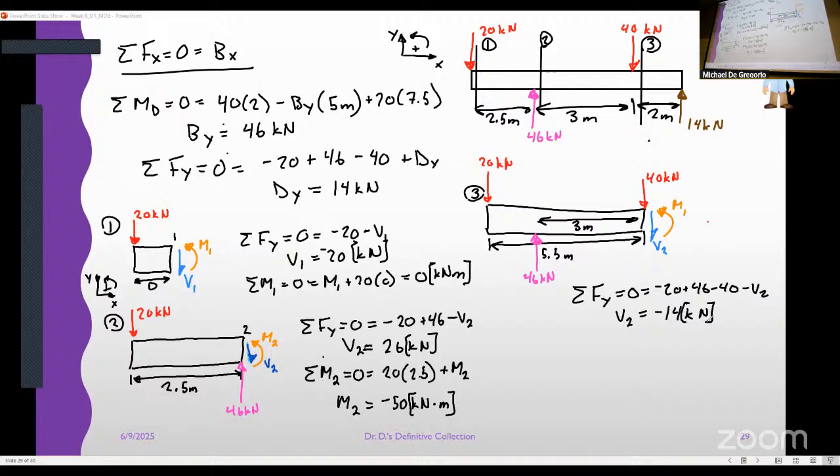And these are point loadings, and if you were to cut this someplace before 3, let's say I cut this here, let's call it 2.5, what if I cut that at 2.5? How does that affect this particular free body diagram? It makes it a little bit longer.